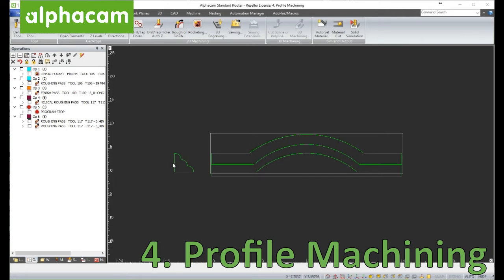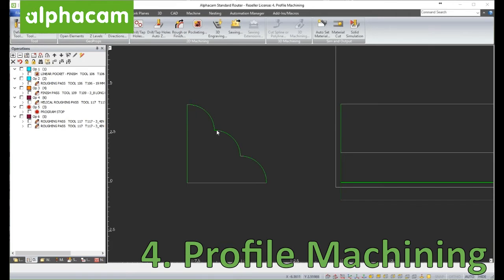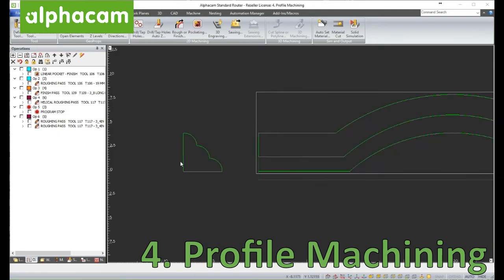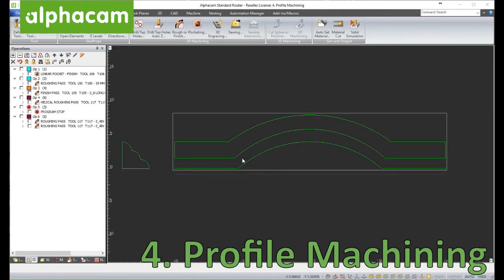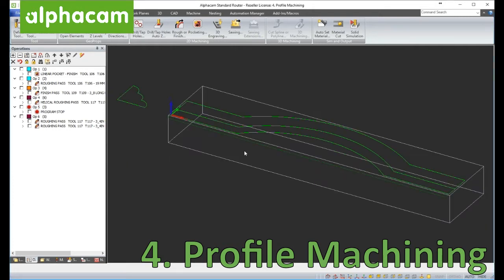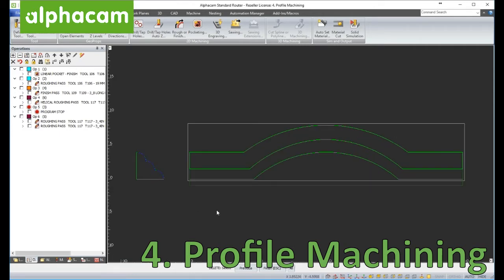However, you would have to get very involved creating the custom knives that your molder or shaper are going to need to be able to run this profile. If you have that need, Alphacam will allow you to create this complex 3D data by creating minimal geometry. To give you an idea, the only geometries I had to create here was the actual shape of the molding and a cavity geometry where I'm going to be removing excess material, as well as, of course, the profile itself, which is the geometry in blue.